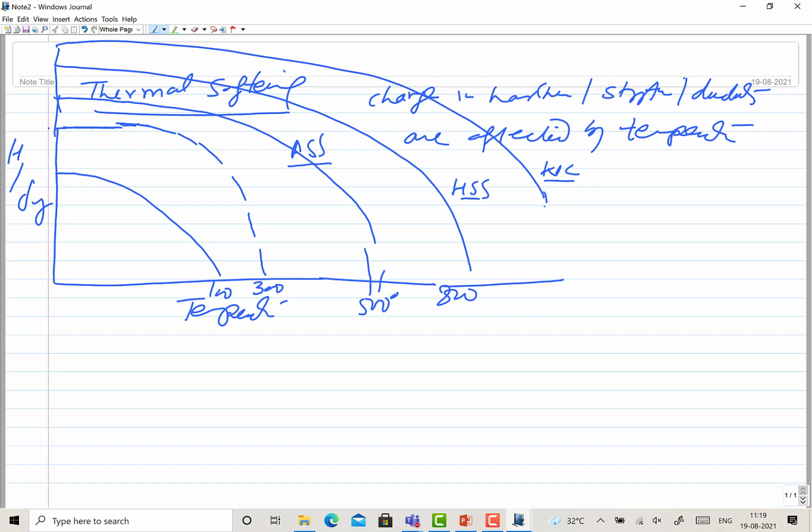There are multiple causes for this kind of change, which may be in the form of metallurgy, the metallic weakening basically, with the rise of temperature. Other factors are recovery and recrystallization at initially low temperatures, then grain growth.